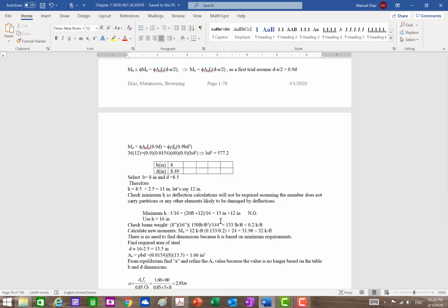And if you add more height, you need less steel. And if you put less steel, you're moving to what side of the phi factor graph? To the left, to the right? Yes, to the right. You're moving closer to the minimum. And that's why your ductility is pretty high. Right? All right.